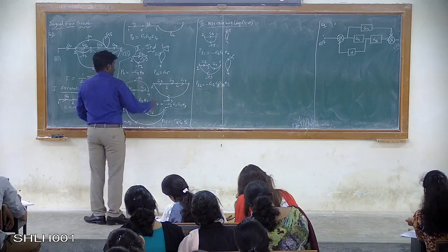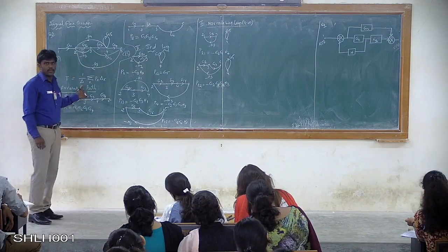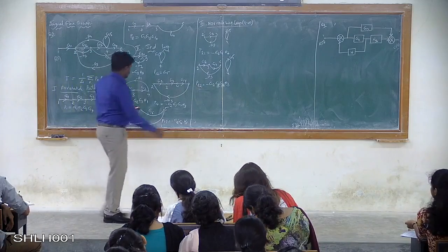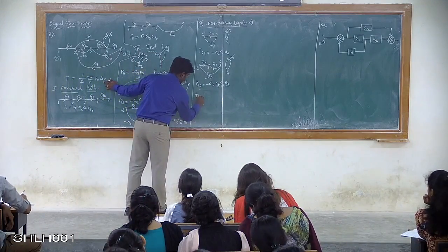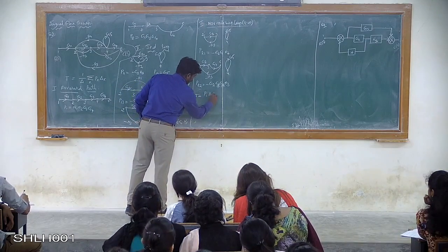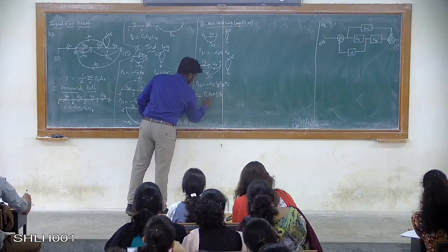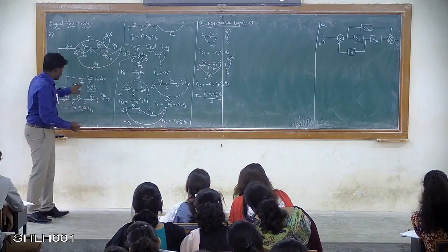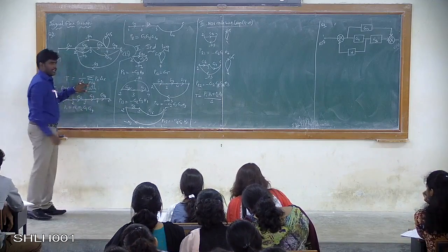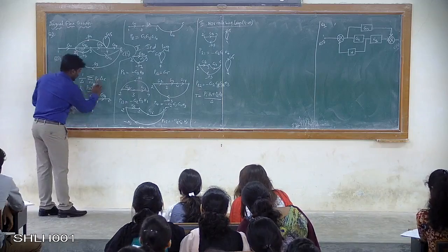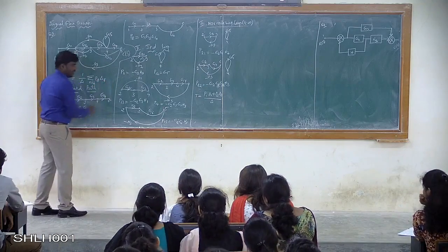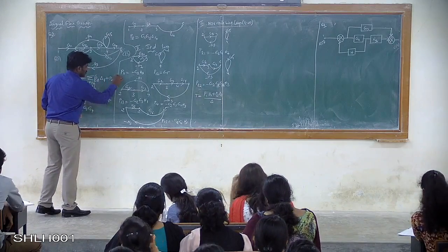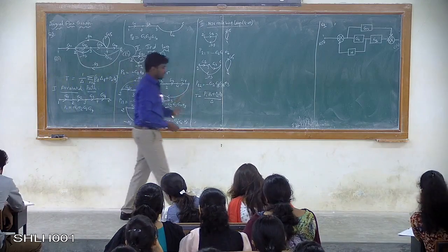Okay. So what is the next thing? We have to write down the formula for the same. Now how many forward paths have we found? We have found 2 forward paths. So my Mason's gain formula equation will be like this: P1 del 1 plus P2 del 2 divided by del, right? As we had 2 forward paths, my K value will be 2, right? So since my K value is equal to 2, P1 del 1 will be there, and since this is a summation, it will be P2 del 2 also. So the Mason's gain formula is written over here.